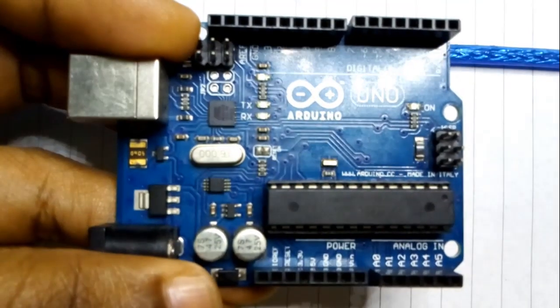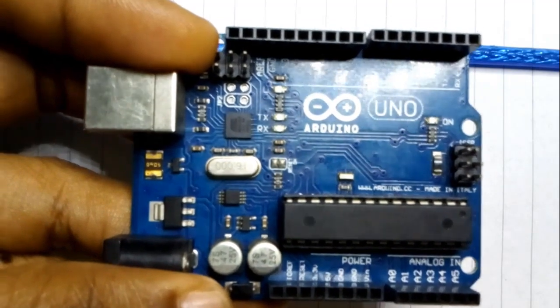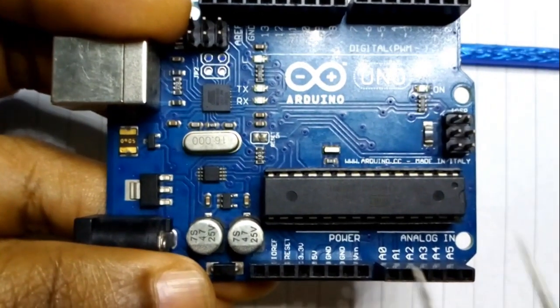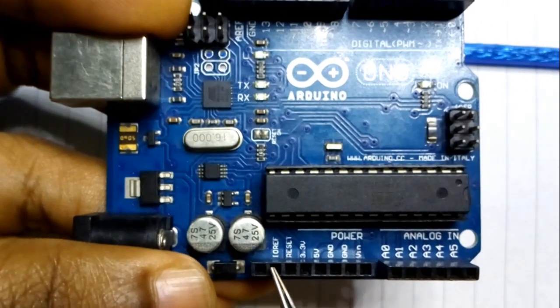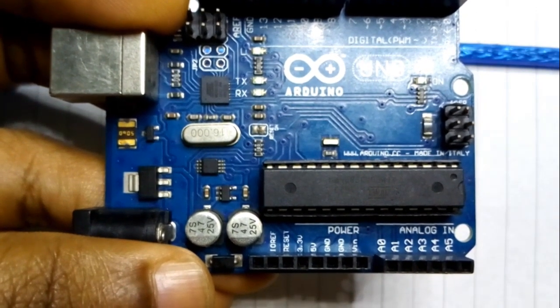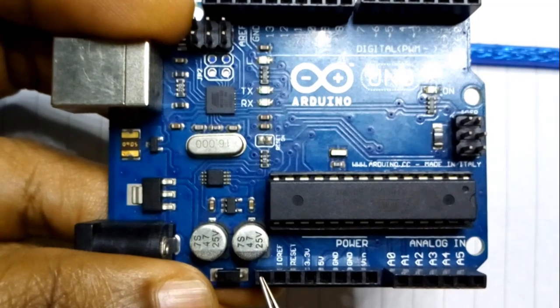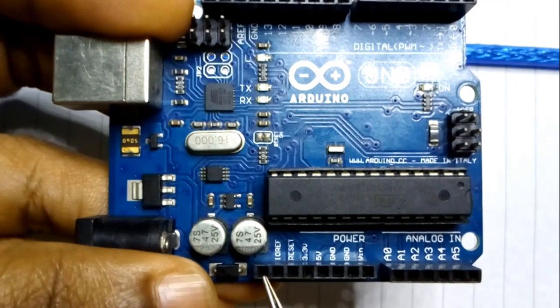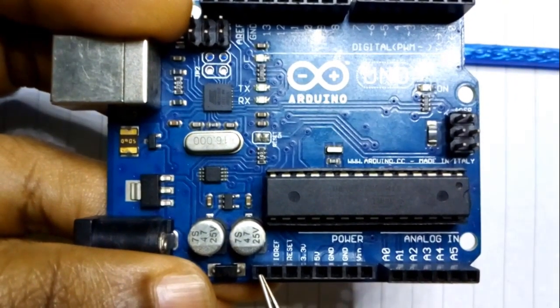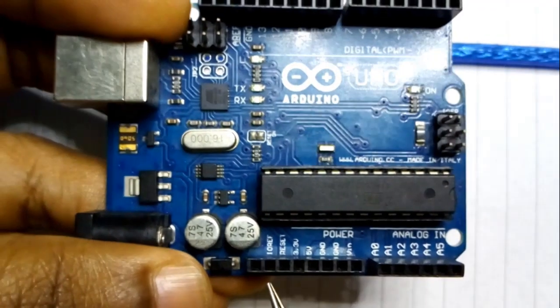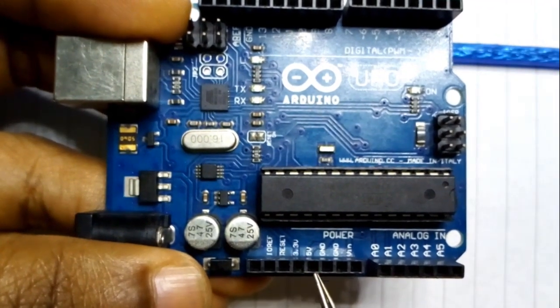So for an Arduino Uno, because it's a TTL device, if we read this IO reference value, we should get something like 5 volts. Now, the pin closer to the IO ref here, you see that it has no label. So it actually does nothing. It is there for future compatibility purposes.